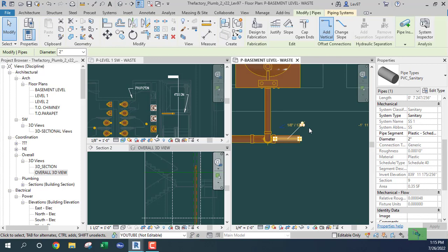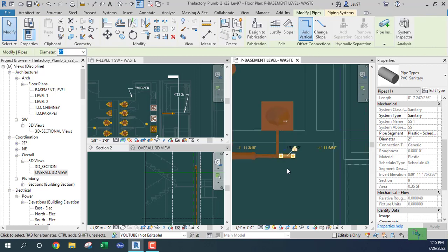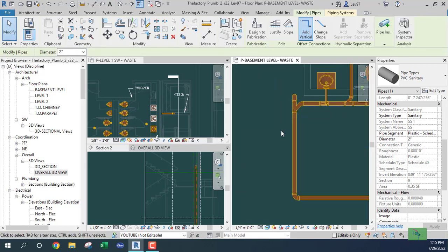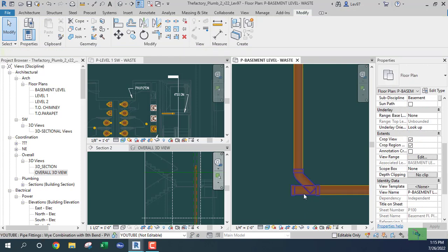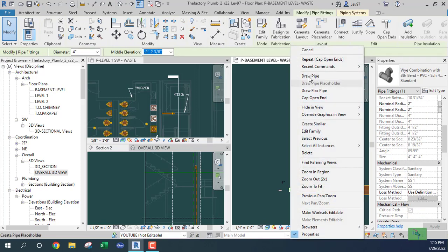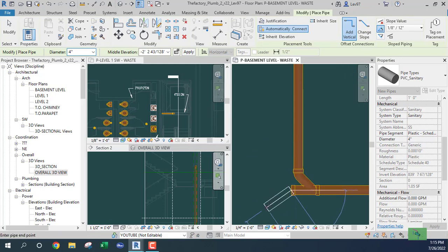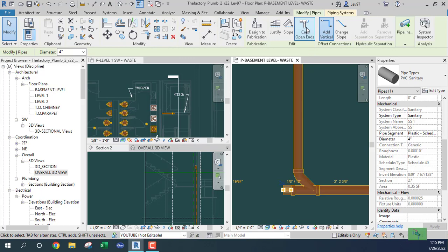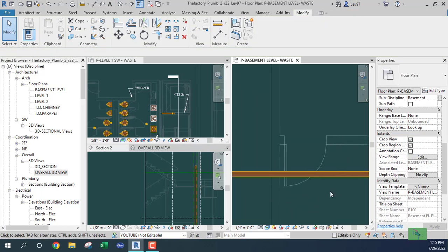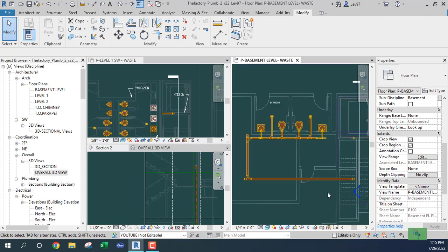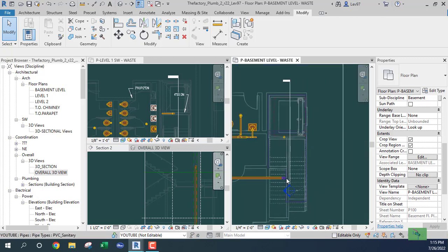Okay. What I'm looking at are my fixture units, making sure everything is being counted for. Okay, 18, and here's another clean out. Okay. Draw that, and we're gonna go slope up and put a cap on this guy. So we are still, and then it goes down. We are under the slab in this case. We're still under. It goes down to the sump pump.